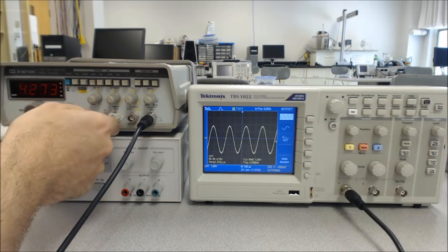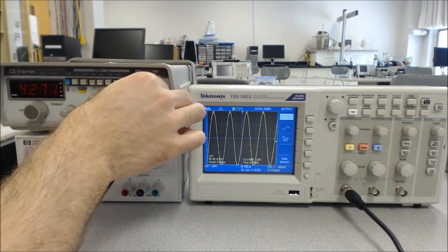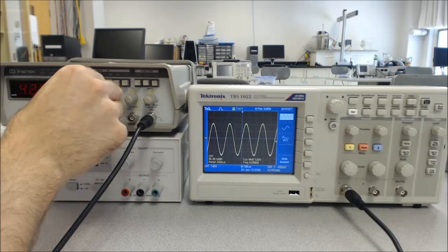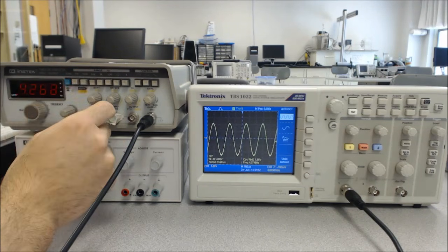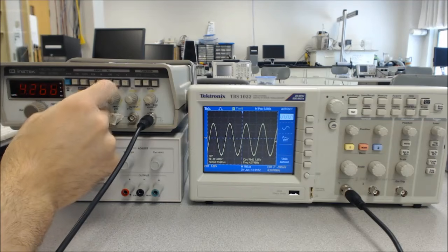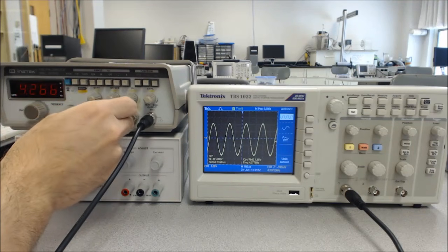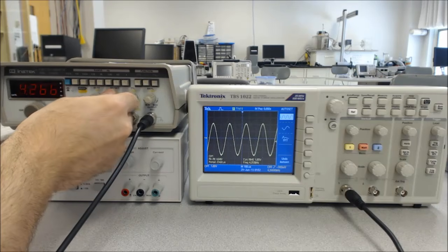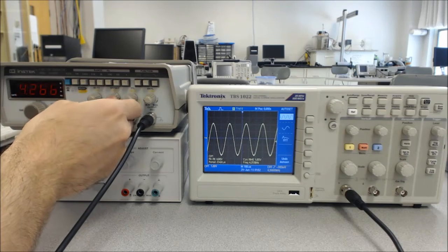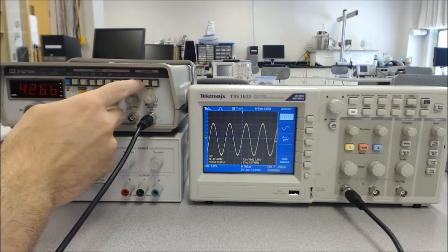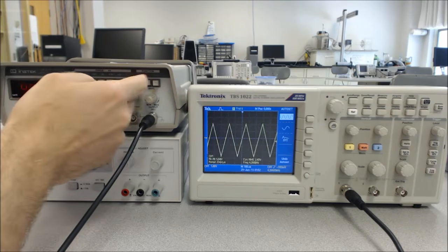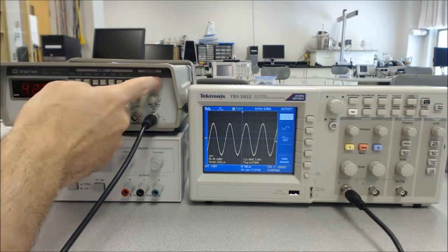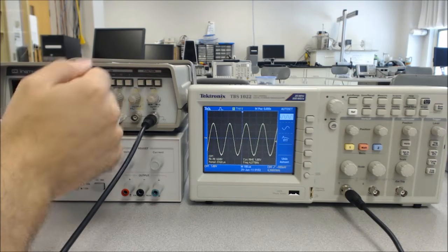There's a couple other knobs here for the amplitude of the sine wave and the duty cycle, which you can see distorts the sine wave. So for the most part, we're going to want to have the duty cycle turned all the way over so that it looks like the sine wave you expect. You could adjust the offset, which we also usually won't want to do. You can also change the type of signal that's being generated. I could create a square wave, which you can see over there, or a triangle wave. Like I said, most often we'll use the sine wave.